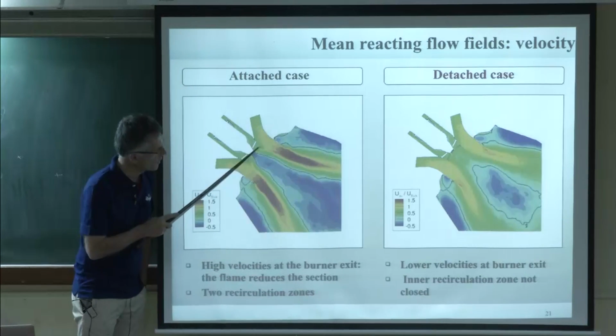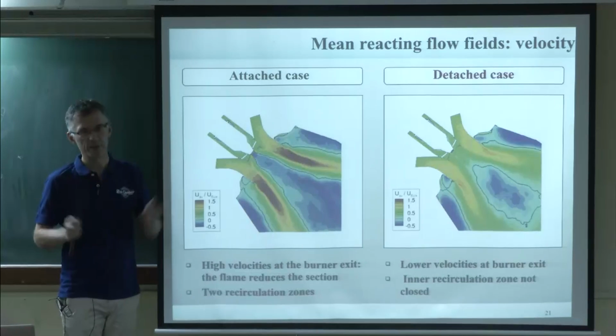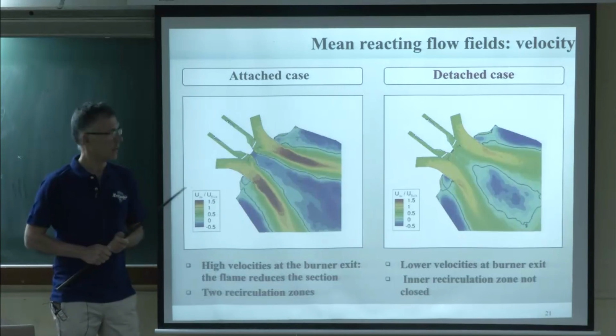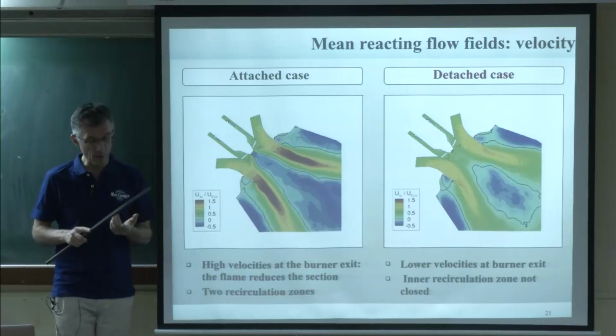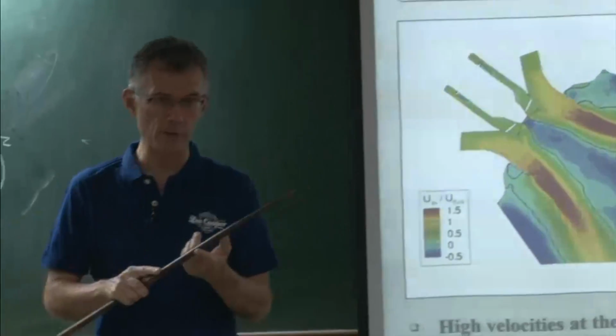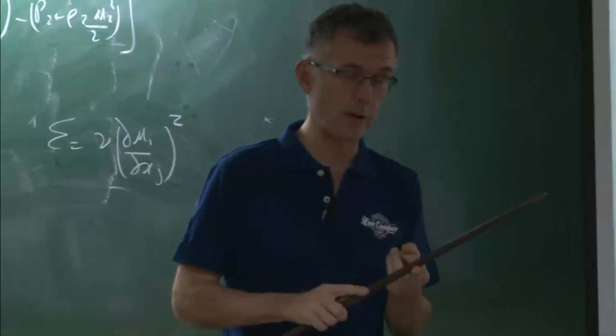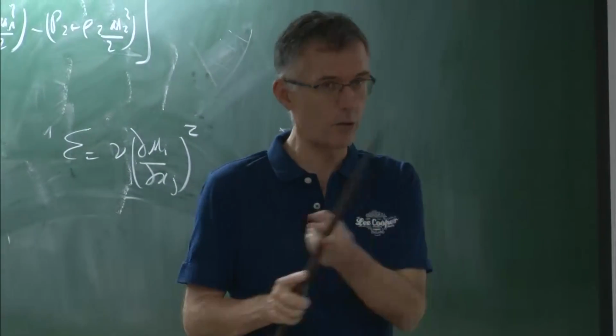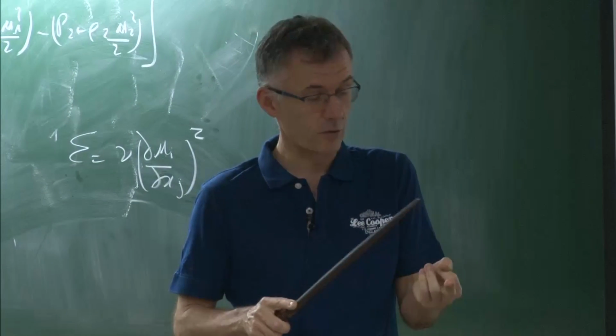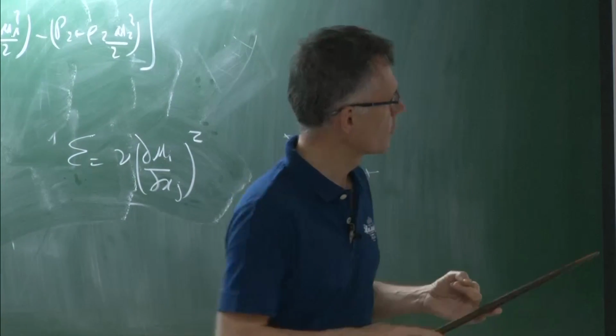If you don't put points here where the mixing takes place, then it's gone, it's finished. So that really means that we probably need to do criteria for non-reacting flows, but then if you go to combustion, we need to think about mixing first, because if mixing is wrong, it's not going to work, and then we can talk about reaction zones.